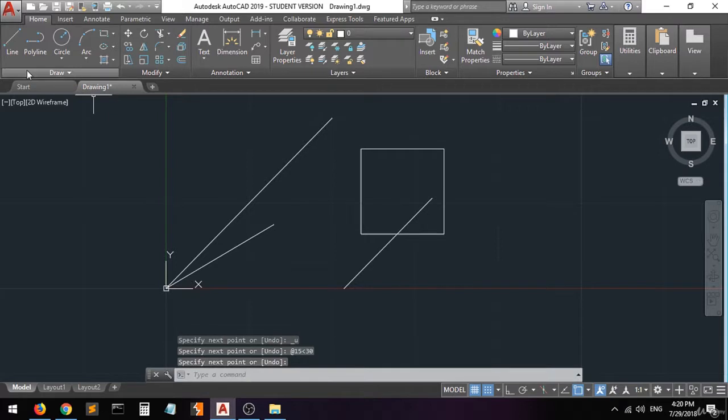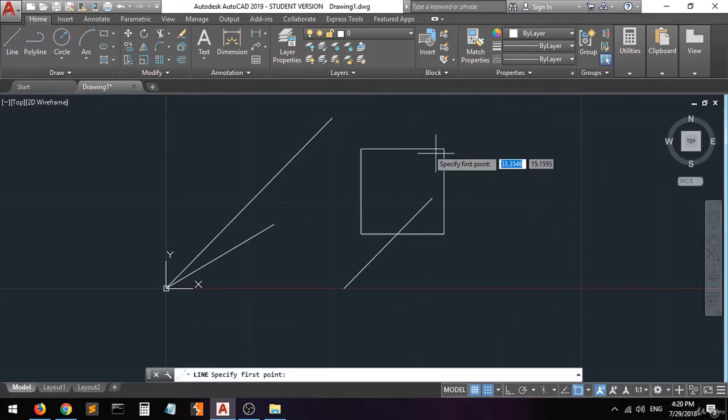Enter. What if we did this? We picked any point on this line and then we did not put the at sign. Putting the at sign will do it relative to this point. But I forgot to type it, for example. Let's just put 15 and then in the angle of, let's assume 45.